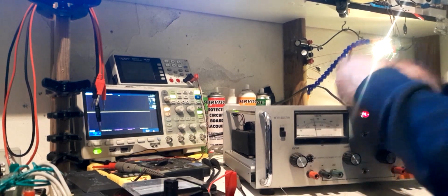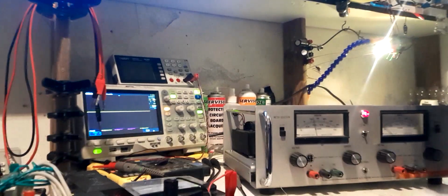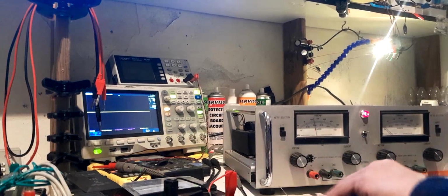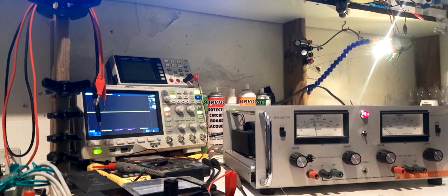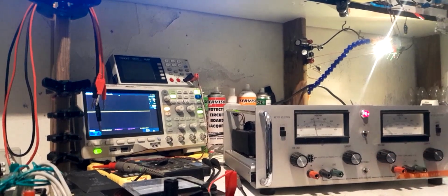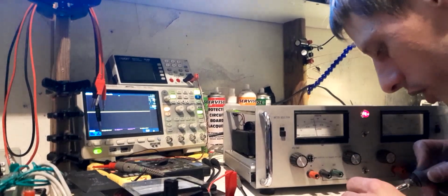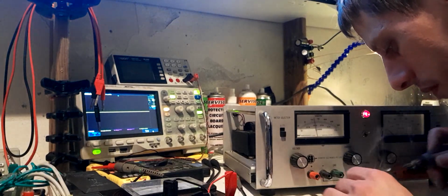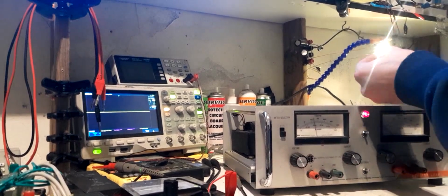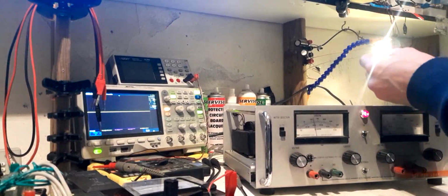Right. Oh, it's exactly what I thought it was. I had a feeling it was this end because I marked a positive there, but me being an idiot, I always get anode and cathode mixed up sometimes. So I just wasn't 100% certain. I thought I'd double check it. Make sure that the stripe on the diode does face this way where I put a little plus on the board, not that anything would happen if I put it in the other way. We'd just have a 0.6 volt reference.